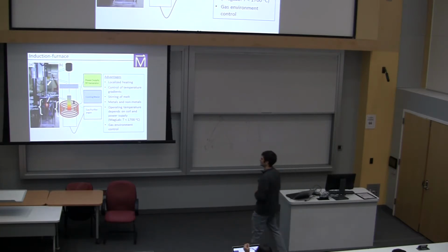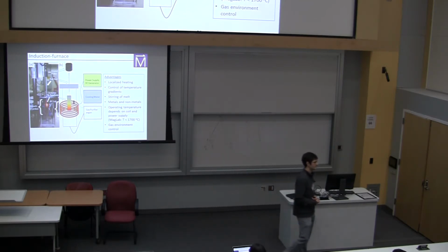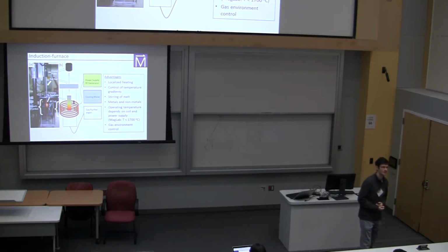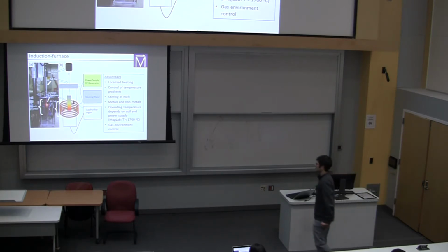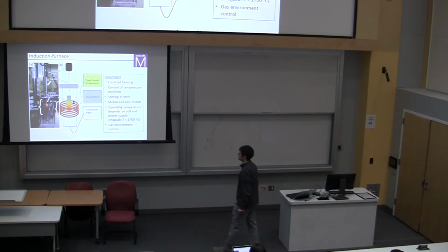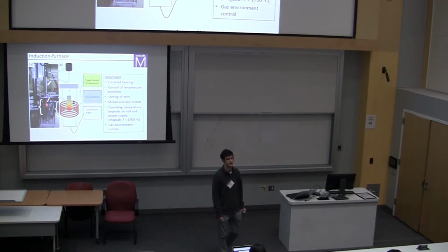So I don't like the argon directly out of the bottle. And you know, even when it says UHP argon, I'm not convinced that that is very clean. I think that what UHP means in terms of the industry standard is that they used a certain method of connecting to the bottle. I don't think it's the actual quality of the argon. So I think it's very important that you have some sort of gas purifier in the circuit before it comes in.